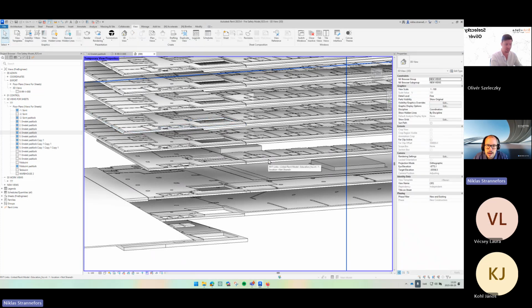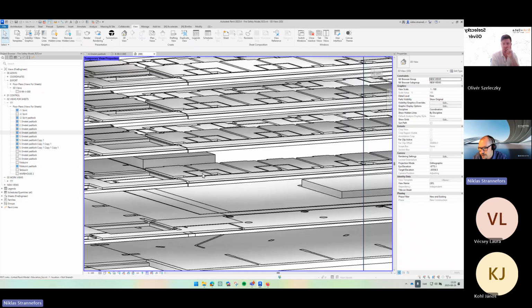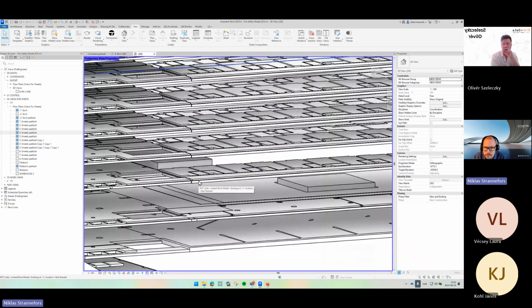And how we want to do it is that we actually want to do the same copy monitor with the structural floors in this case, because they are here and they are larger. If we zoom in, we can see all the architecture floor, which is just around or inside the rooms. We don't want to use those. We want to use something that goes around the entire building. We can manually draw if we want, but I'm going to do the copy monitor.